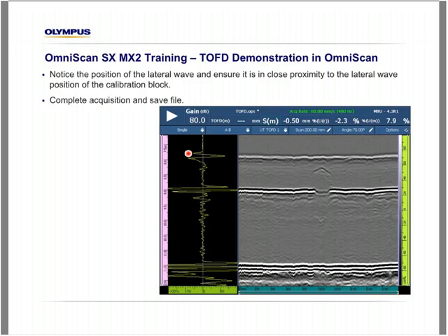The pipe is not mismatched for the fit up. It doesn't have any distortion. It's basically the same condition as my calibration block. When that is true, I know that my PCS value is still valid and my wedge delay is still valid as well. Notice I acquired the data in an uncalibrated state. The pink ruler that we see here is in microseconds.